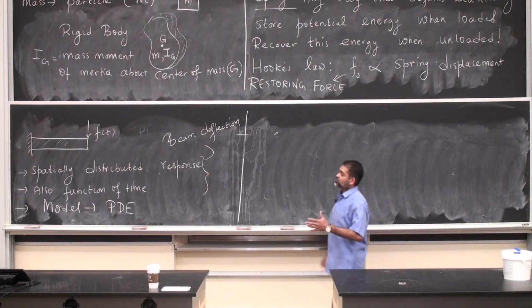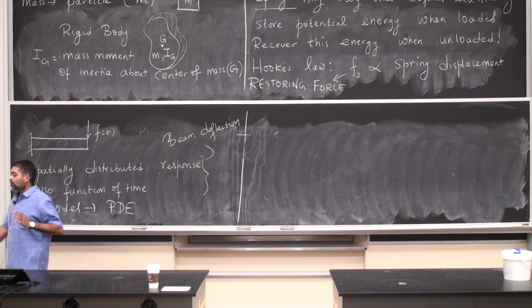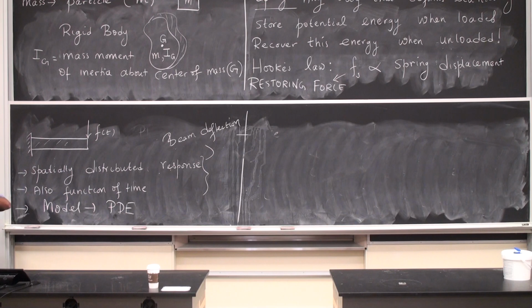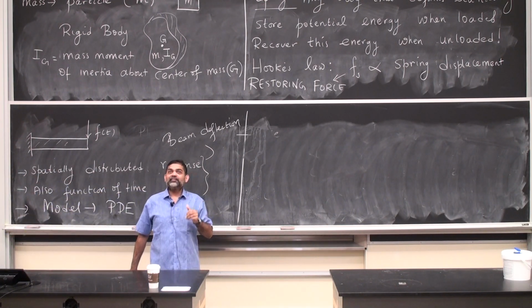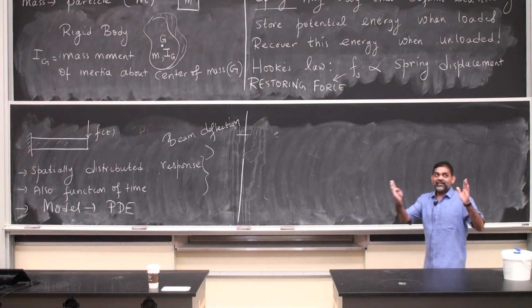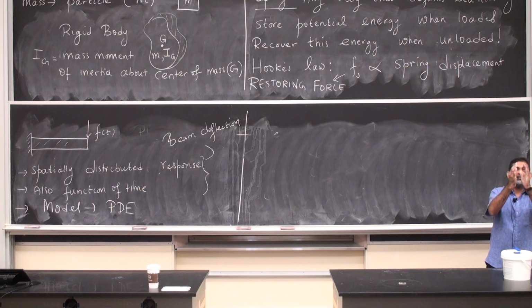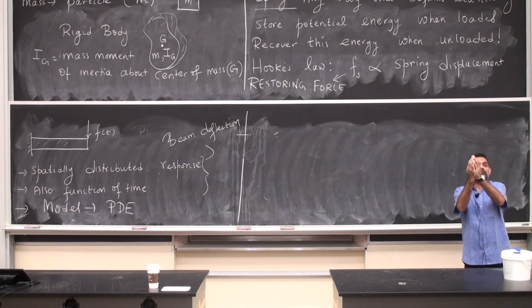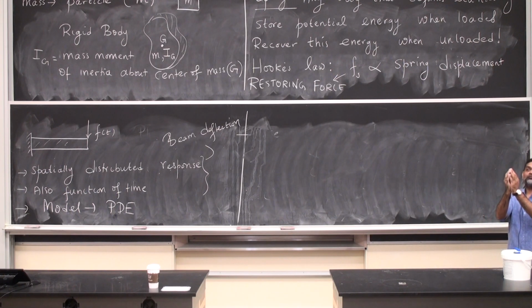My business is to take something that is as complicated. It may not look complicated to you, but it is pretty damn complicated. I take something like this and I simplify it using the tools of mechanical systems. Linear passive elements. Here is what we do. Okay? Take the entire beam, lump the mass of that entire beam into a single particle. So that that beam now is going to be drawn in the form of a particle with mass m.